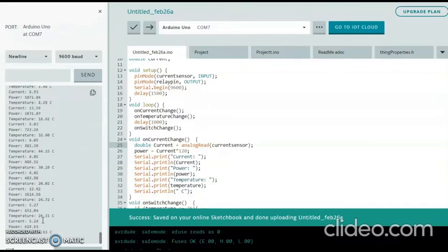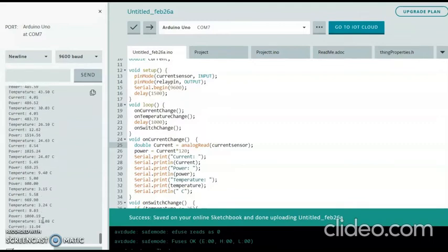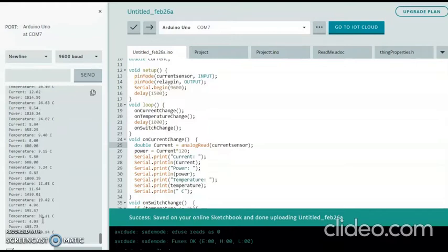And when it's not running, it's probably 600 to 500 and decreases to zero. But this has to have a cool down time. But since the change of temperature is pretty rapid, and there's an error with the temperature sensor, it doesn't allow the power to go down to zero when the heater is fully turned off, because it only takes almost 3 to 4 seconds for the heater to turn on again after it turns off.